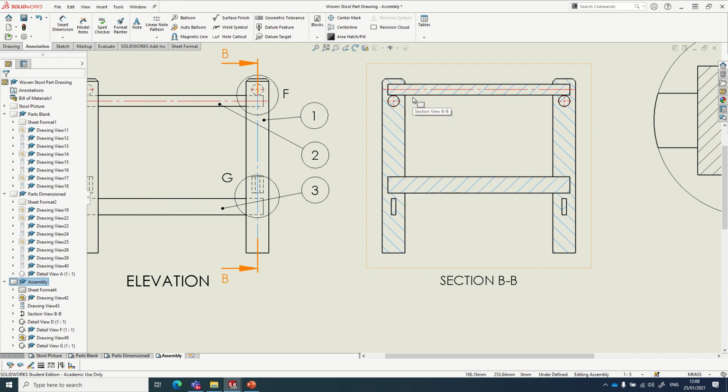So it makes it a bit easier to see what the actual joints look like, that we actually have our X-ray vision essentially. You can see as well in the section it should be correctly hatched. So hatching is this pattern that we see here, and basically each piece here should have a different type of hatch pattern. So this one here is a 45-degree line going in this direction. This one here goes in the opposite direction. And you can change around the spacing of the actual hatching, or instead of having a single line here, you could have a double line there like that, or this could be a double line here compared to up here like that. But basically each piece should have its own identifiable hatch pattern.